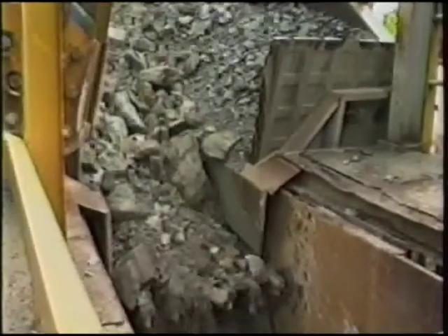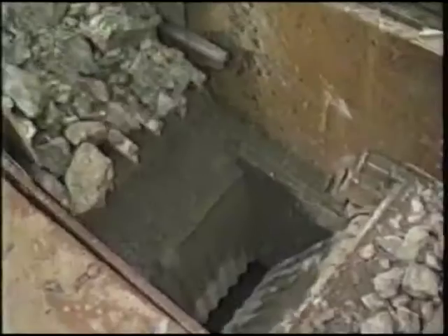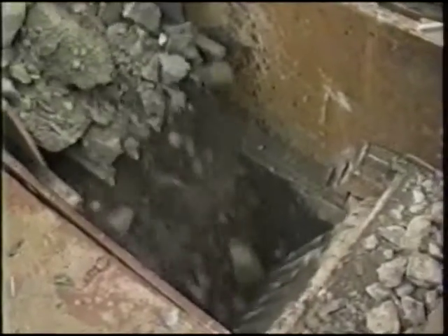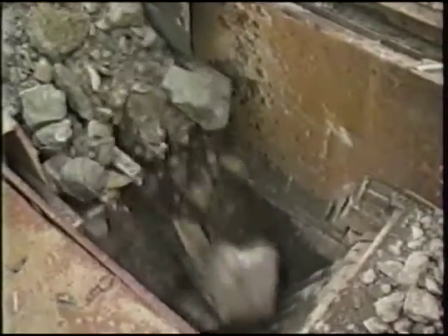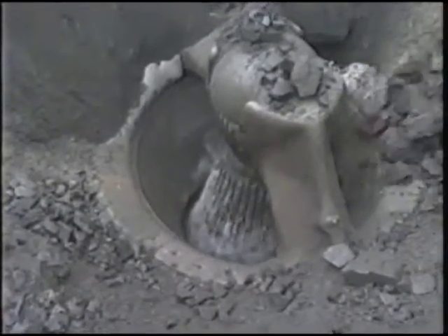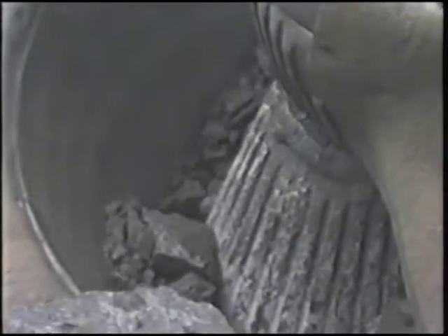In most instances, shot rock is moved from the primary loading hopper to the primary crusher by means of a vibrating feeder. The two types of primary crushers most commonly used are the jaw crusher and the gyratory crusher. A jaw crusher, as the name implies, utilizes a movable jaw, sometimes called a swing jaw, to crush shot rock against the stationary jaw. With a gyratory crusher, shot rock falls into the bowl. It is crushed by the eccentric motion of the crushing head.